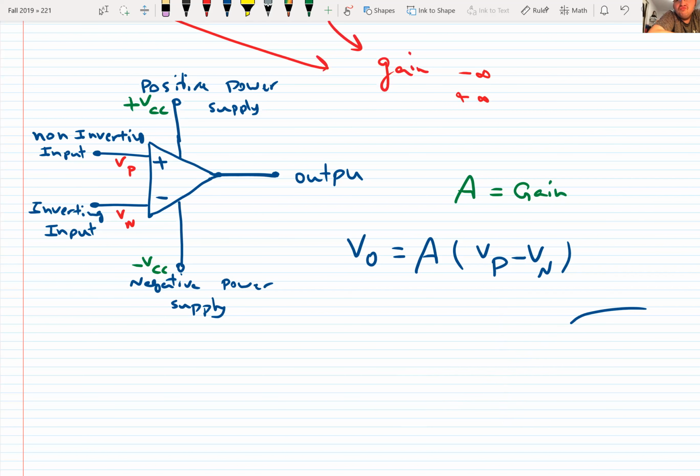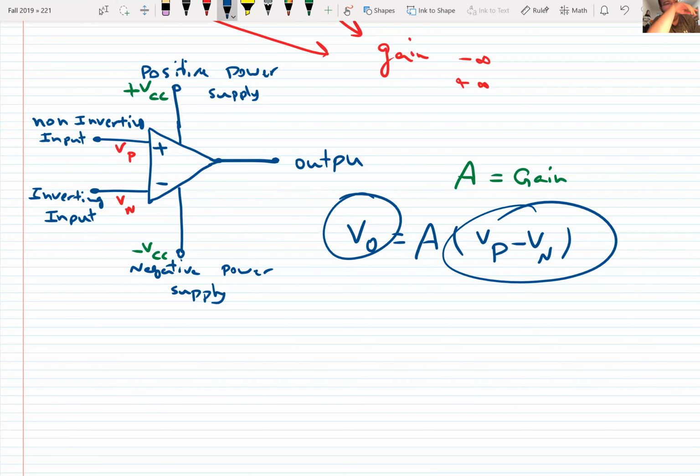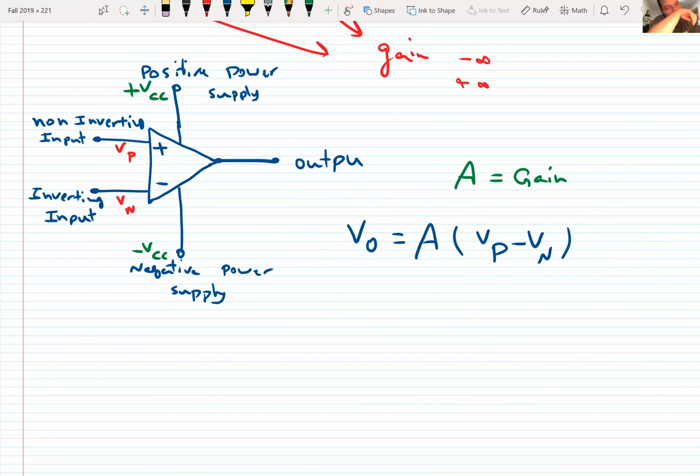Okay, so that one was for the resistor. What about the amplifier? The characteristic of an amplifier is not plotted as a function of current and voltage, because the variables of a resistor are current and voltage. But here, the input of the amplifier is Vp minus Vn, and the output is Vo. So we need to characterize an amplifier based on these two variables.